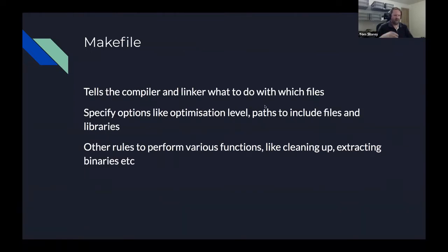So that's what I've imitated with my little bootloader script. I've told it that the first instruction will be at address 400 hex. So in a way I've just emulated the CPU coming out of reset, but obviously it was not necessarily running out of reset.